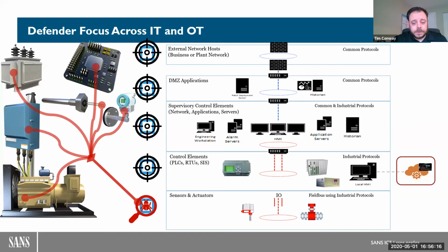Finally, kind of the sensor to sensor, Jeff had demonstrated some ability to go in and modify some scaling factors on devices directly to manipulate how they operate within an engineered and designed system that could cause some issues, modifying them through the data tables of the industrial control system devices that they're connecting to. So you're not necessarily touching the logic itself. You're not necessarily manipulating these sensors or these kind of digital assets that are deployed throughout the field. And you're not manipulating anywhere on the network communication paths either. You're causing that manipulation within the device.